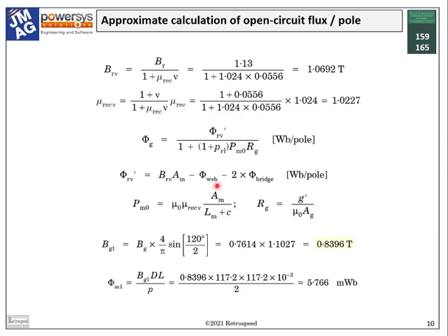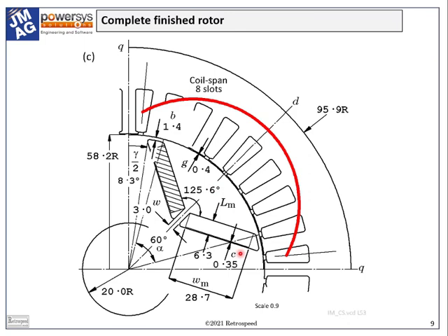So we're going to lose the flux from approximately 11.6 millimeters of magnet width. And since the overall magnet width is only 2 times 28.7 millimeters, that loss represents over 20% wastage of magnet. That is a shocking figure, especially in view of the high cost and scarcity of rare earth magnets. We will return to have a closer look at this issue a little bit later in the video.